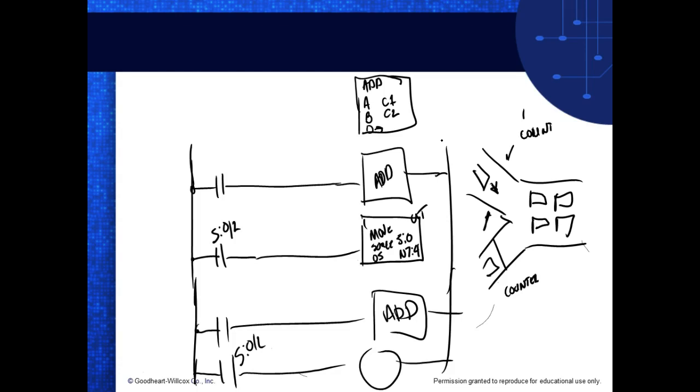Or if I exceeded the range of my numbers, I'm going to have to do something, because if I've got an overflow, guys, you've got an overflow. So you've counted up to 65,535, right? You understand? And you add one more. Well, what's the thing going to do? It's going to roll back around to 0. You're going to lose your whole count unless you can figure that out. Okay, I got an overflow. Well, what you can do now is stick that number somewhere, and then let it roll around.